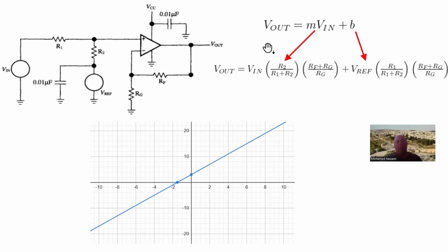And so one way to do this is to generalize with these amplifiers. We have one case where the DC offset and the slope or the gain are positive, and that's this circuit in here. That's where the input and the reference are both on the non-inverting port. It's a non-inverting op amp, so it's always going to be 1 plus the ratio of these resistors as your gain for both this one and this one. The only difference is that the DC level, this reference, is split between these two resistors at this point.